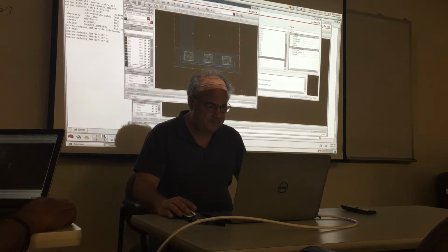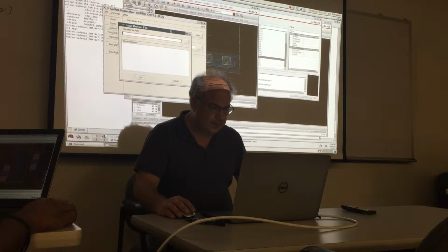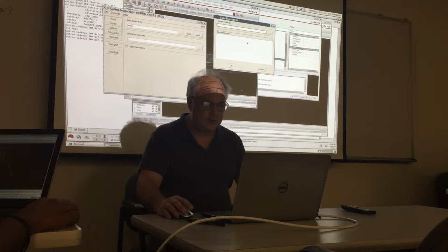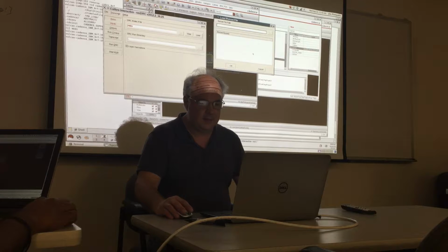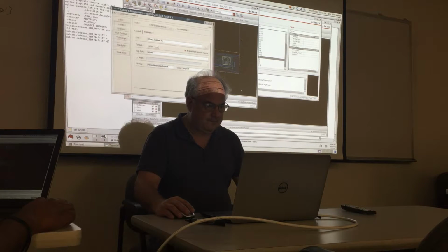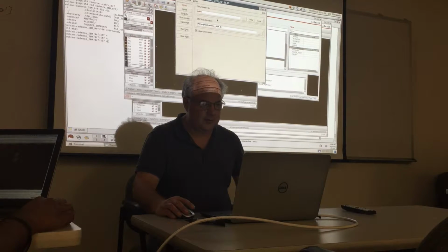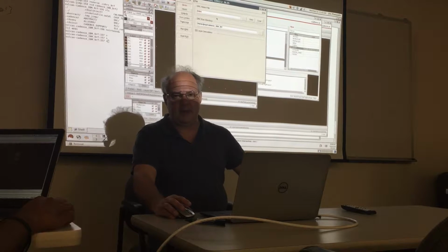But there it is. Okay. And so when I think what it'll ask you initially is whether you want to load a run set. If you don't have one, you just hit cancel. Okay. And so the problem is that it defaults to mostly good things. The one thing it will not have is the rules, right? Because it doesn't know where the IBM PDK is.